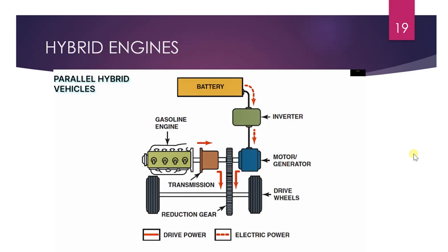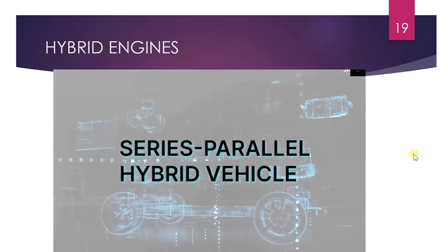In most cases, the electric motor is used to assist the internal combustion engine. Because of this, the size of the electric motor and the engine can be significantly reduced. However, there are a few disadvantages in this variant too. The design of such a vehicle is extremely complex. The design involves complex software and gearbox design, which is needed to seamlessly blend the energy from the battery and the IC engine.